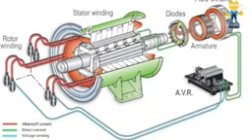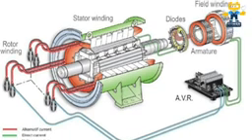Now what happens: once the voltage is generated, it gives sensing voltage to the AVR, and once the AVR gets the sensing voltage from the main stator, this reference voltage generates the AVR DC voltage, and this DC voltage excites our exciter stator windings.